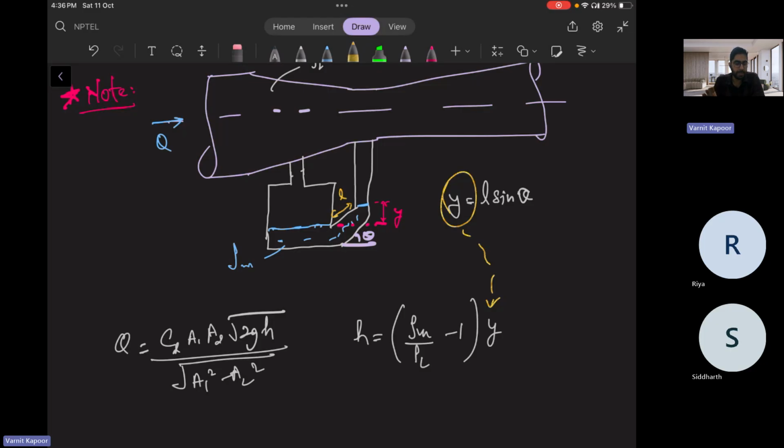So it's nothing but a circular plate with a concentric sharp edge hole at the center, and it is used to measure the discharge in pipe flow and tank openings. Because of the sudden obstruction in the device, we have seen vena contracta formation. The flow has inertia, and with sudden compression or expansion, eddies form, the flow gets separated and high losses occur. That's why the discharge coefficient value is required to be computed.